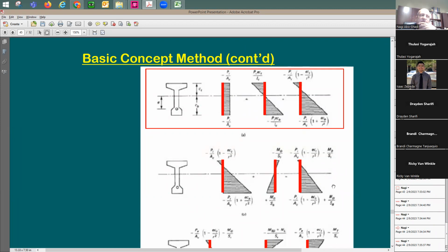I'm going to start here to apply the load. So in the second phase of loading, I can just take this load distribution and transfer it here. I'm going to say, okay, now I have pre-stressing. Now I need to add the dead load to it. What does it mean by dead load? Dead load here, in pre-stressing, is going to be the self-weight only, and that's it. No additional dead load is going to be added to it. So what's going to happen? I'll just take the stress distribution, and we're going to add here the effect of the dead load. You add the stress value here to the stress value here, put it right there. Then you add the stress at the bottom with the stress at the bottom, and you put it here.